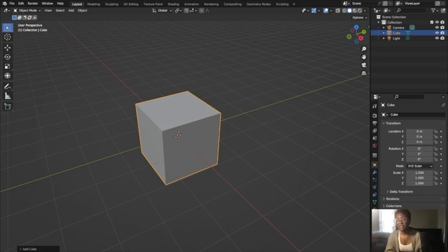Each face of a mesh can have many UV textures, and each texture can have individual images assigned to it. When you unwrap a face to a UV texture in the UV editor, each face of the mesh is automatically assigned 4 UV coordinates. These coordinates define the way an image or texture is mapped onto the face.